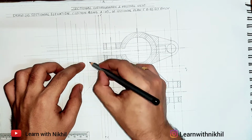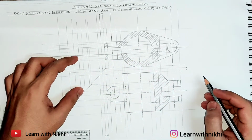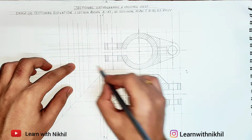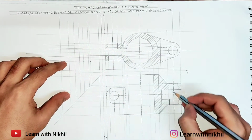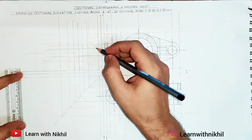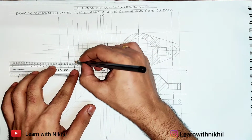From the front view we'll get the height. So this part is from the top view. Also this part we'll get the projection. We'll mark the point. So as you can see, the height from the front view and the width from the top view. Make this part dark, as this will be the first part which will be visible from the right hand side view.